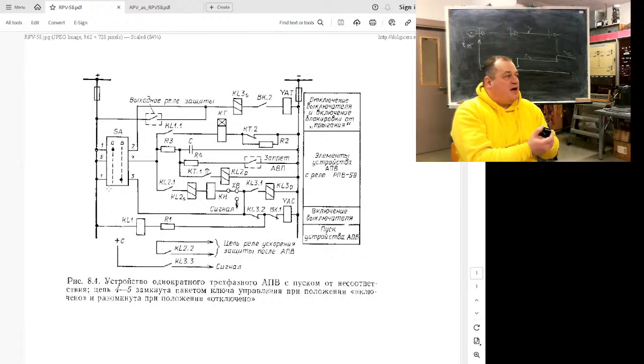You need to prepare the circuit. This prevents operation from some kind of disturbance. It's one of the measures to prevent false operation. A signal to connect or disconnect the line can only be passed if we have the line under operation, the switch is on. This is the line on position, or transformer on position. To disconnect the line, you need to first put the switch into the disconnect position and then send a command.